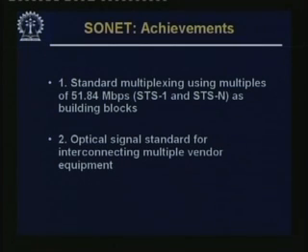Secondly, it also first stated the optical signal standard for interconnecting multiple vendor equipment. The point was, previously at lower rates they were all electrical signal standards. SONET has both an electrical signal standard as well as an optical signal standard, and in this optical signal standard it was possible to bring together multiple vendors to agree on a particular format.